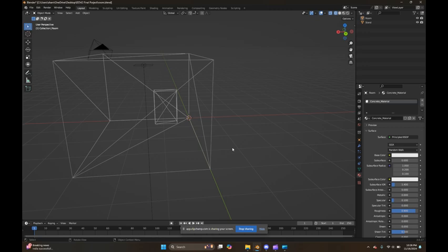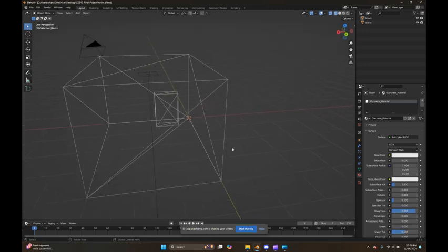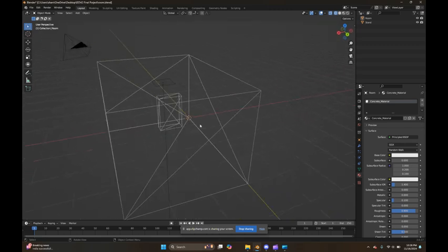For this example, I've created a very simple model of a room, which is of size 3 by 4 with height 2.24 meters. And we have an obstacle within the room, that is a shoe rack, which is made of metal. So what we do here is we create the room and then we allocate the material it is made of, and then we use ray tracing in MATLAB.